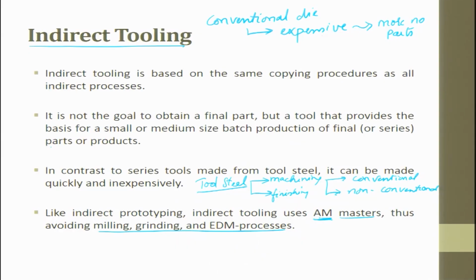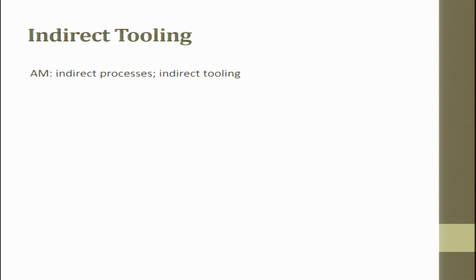So, if you decide to make a metal die, the route itself takes 6 months, and it is not necessary that after 6 months whatever you make gets accepted by the customer. Though we say modular designs can be followed, finally the shape, size and inserts whatever you make have to be properly planned, which takes a long time. But if you follow the additive manufacturing route, that can be achieved very fast and we look for outputs.